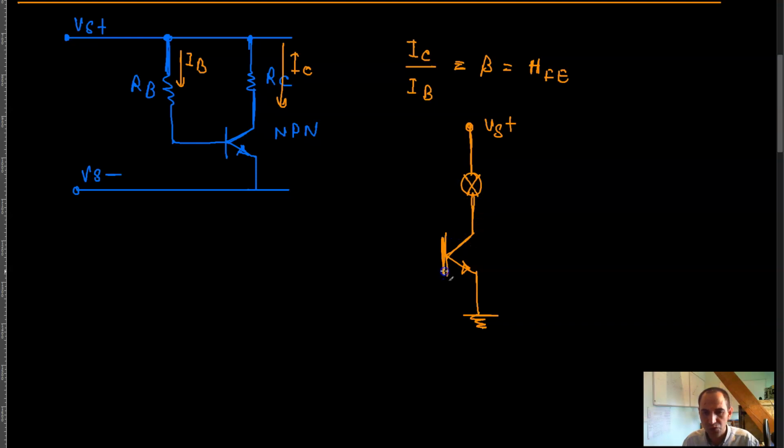So now what I can do is connect this base to a resistor in order to control the base current, and then I can give this to the positive supply voltage, right? Which is essentially pretty much what I have done over here, meaning that you can see that the emitter goes to the ground, the collector goes to the supply voltage through a load over here, and then the base goes through the resistor to the positive supply voltage.